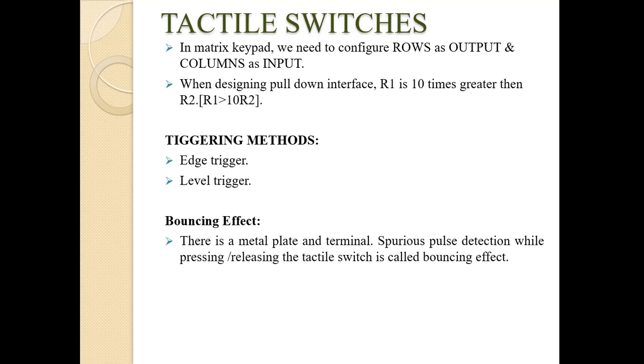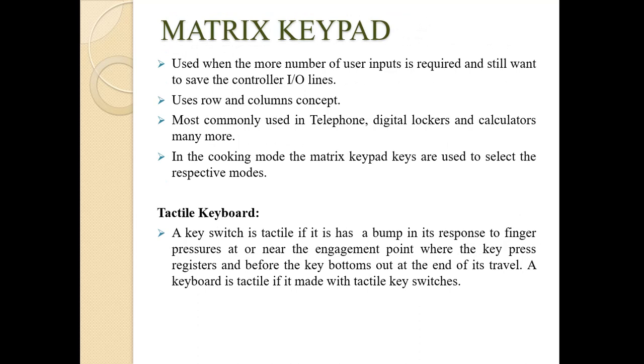Bouncing effect. There is a metal plate and terminal. Spurious pulse detection while pressing or releasing the tactile switch is called the bouncing effect.